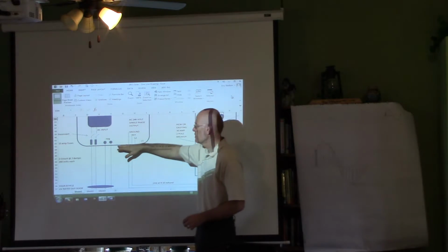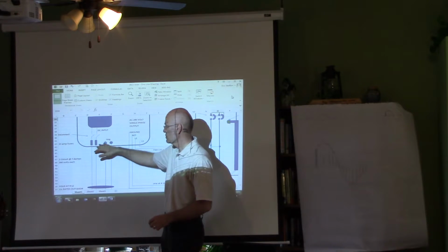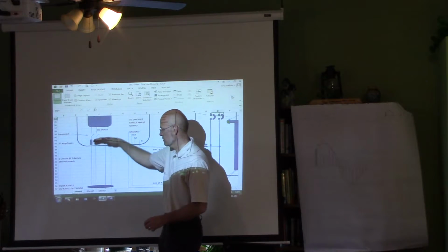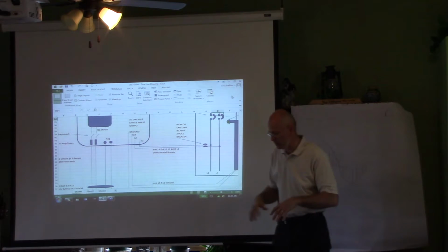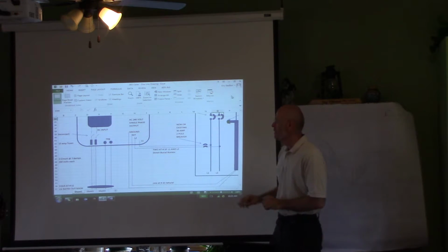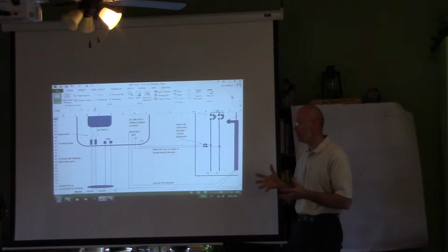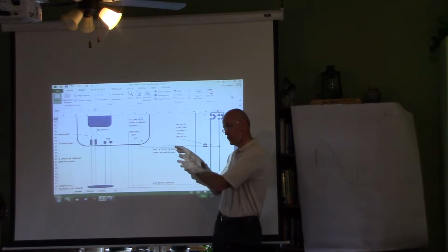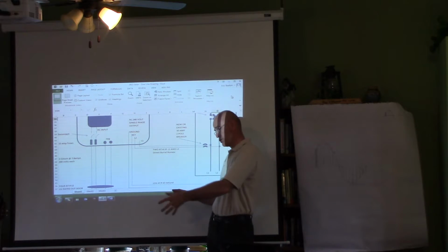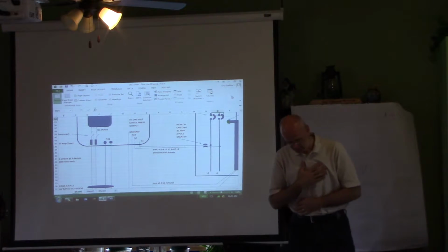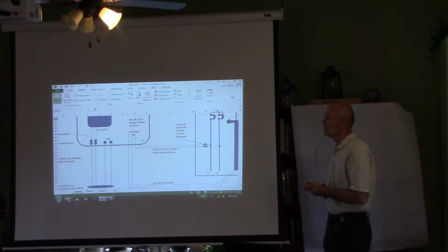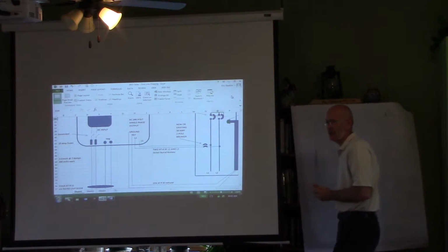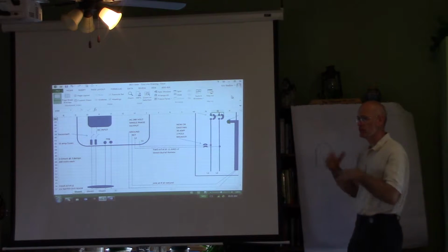When it shuts off, then it shunts the solar panels, and its little water tank is full and it can't do anything, it's disappeared. That's an on-grid system. If you had an off-grid system, that energy would go to the batteries, and the charge controllers would take the AC, convert it back to DC, and charge whatever battery system you had. We don't have that. So being an on-grid system, it needs a reference point. That's the key to that answer. And it's lost its reference point, so it shuts off.